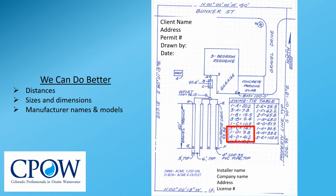The chart provides swing tie information from points 1 and 4. Point 1, the southwest corner of the garage, is 9.8 feet away from the distribution box. And point 4, the southeast corner of the shed, is 41.2 feet away from the distribution box. Using a tape measure, you could swing tie these 2 points and easily locate the distribution box.